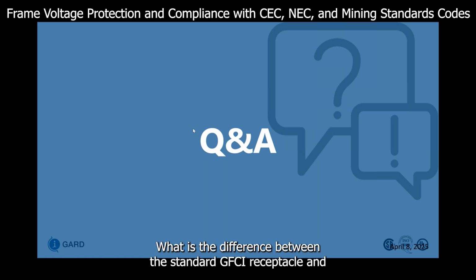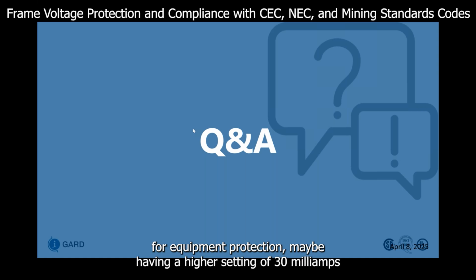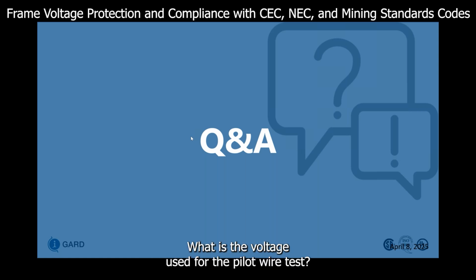What is the difference between the standard GFCI receptacle and the GFCI receptacles used for equipment protection? The GFCI receptacle is tripping at 5 or 6 milliamps typically for people protection. The GFCI receptacles used for equipment protection may have a higher setting of 30 milliamps or 20 milliamps, depending on which UL code requirement you're trying to satisfy. I believe it's 943.